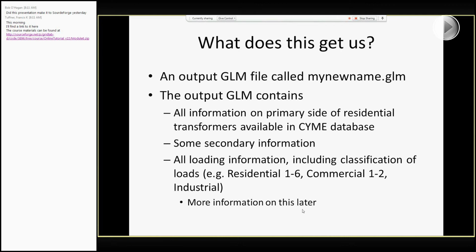This is true because most of the commercial solvers at this point don't support past the primary side of the transformer, down to the 120/240 volt system. My understanding is that Windmill now supports that level of detail, and some of the other commercial vendors are starting to support that also. But at the time we created this a couple of years ago, that wasn't true.